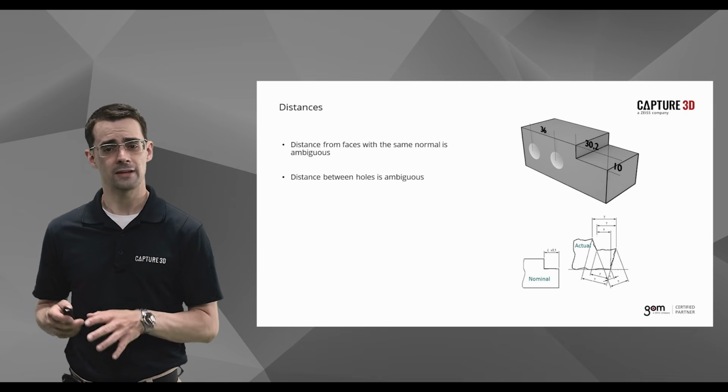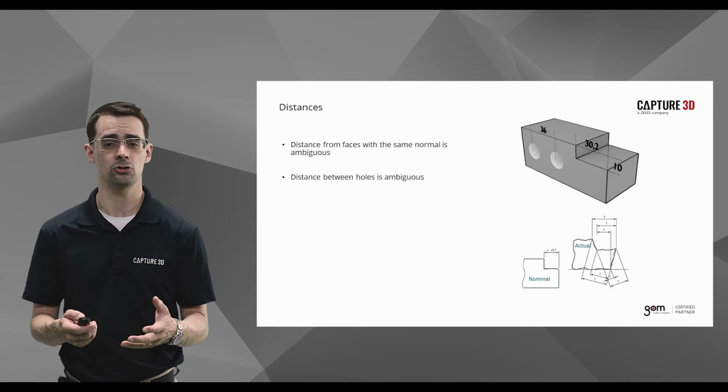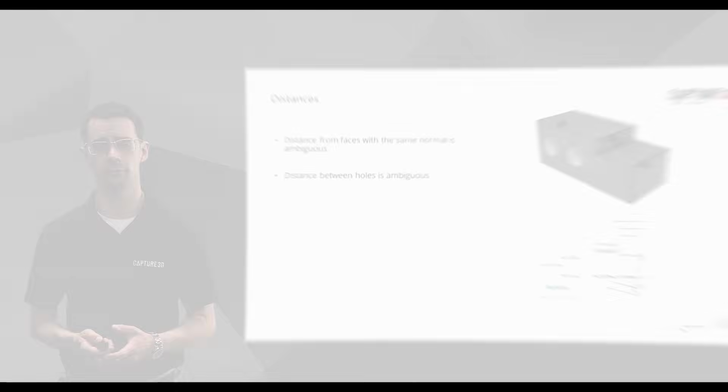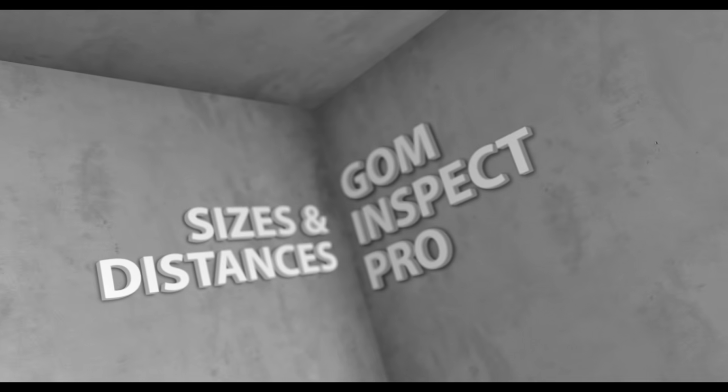These imperfections are exaggerated here, but for parts with tight tolerances, your measurement technique and tools may incorrectly classify the part. However, once we add GD&T to the mix, we remove any of that ambiguity. We now have clear and defined tolerance zones and the locations for these features. With the ambiguity removed, there's only one correct way to measure this part.